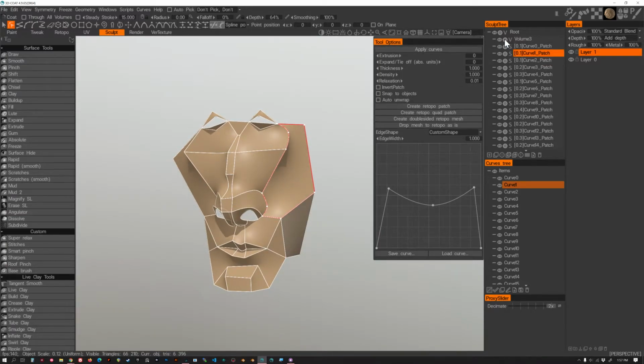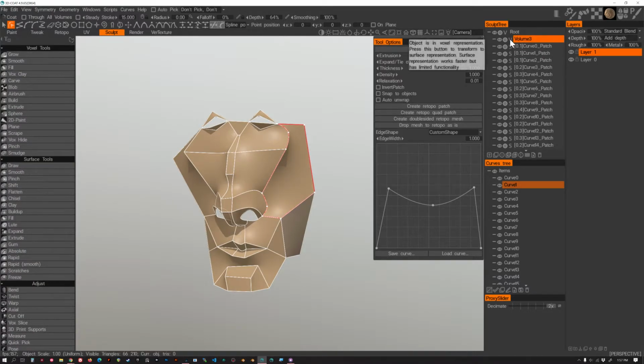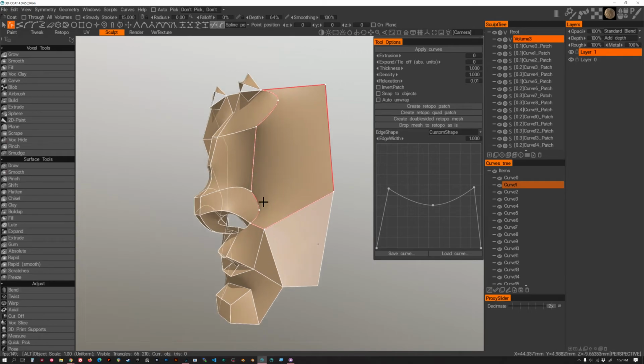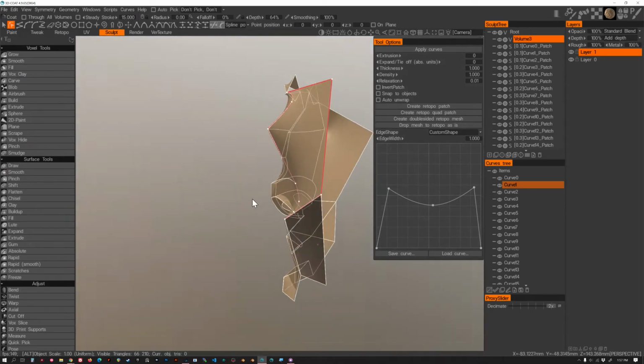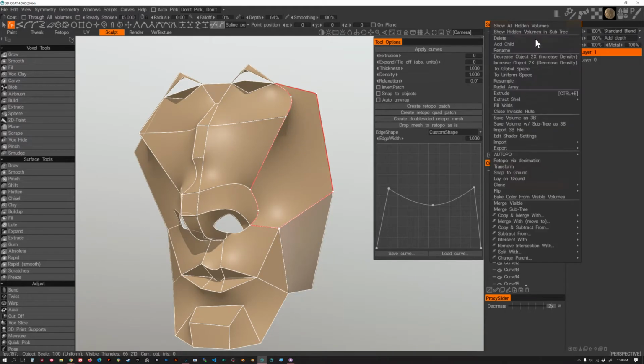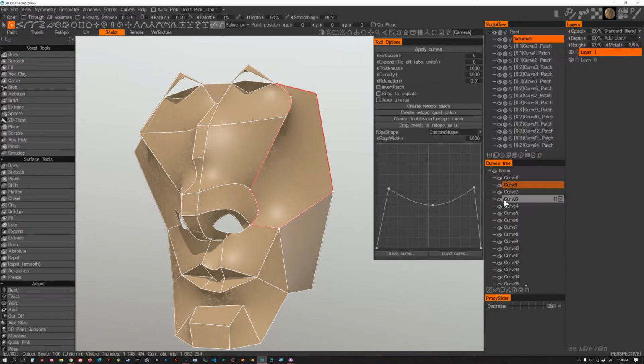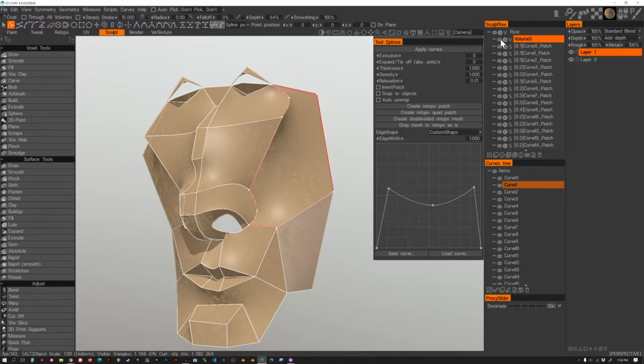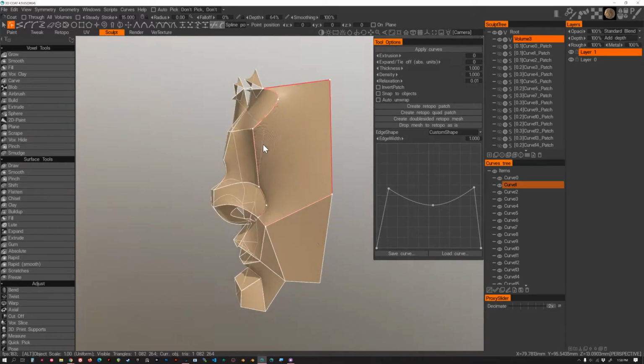So one thing I'll do before I continue on, I'm going to go into this layer. This layer at the top of my sculpt tree is empty, and I can leave it in voxel mode. I imagine that all of these faces are too thin to fully work. So I'll go to merge visible, hold Alt and click on this layer. Actually, I can still see it.